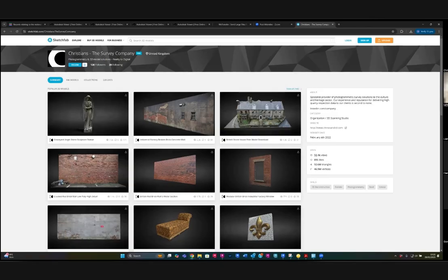People tend to know that I'm quite vocal about equipment salespeople selling things that can't actually achieve what they're saying. A lot of people will say, "Oh, I'll get you a topographical survey, but I'll do it with a drone, and I'll get you 1 centimeter accuracy," which in the real world isn't achievable. It's hard to achieve that with proper land survey equipment like Total Station and GNSS, and knowing what you can and can't achieve is really important.